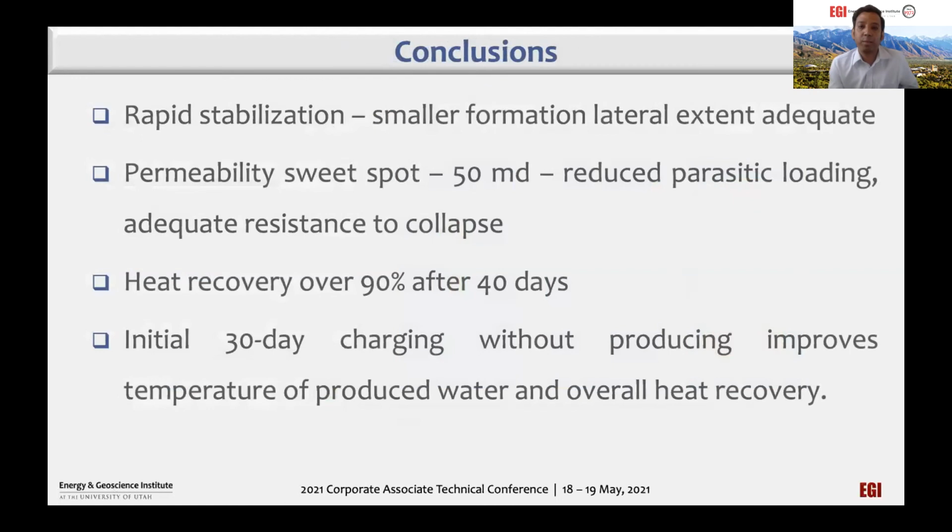So the conclusions from these preliminary studies are, we have noticed that pressure during the stabilization, during shut-in, quickly comes back to initial reservoir pressure. And also we have noticed that there is a small extent, that means for our operation, for our injection rate, it was only like 25 to 30 meters from the wellbore radius. We have also conducted sensitivity of the permeability, and we noticed that only like 50 millidarcies is enough for this type of studies, type of storage.